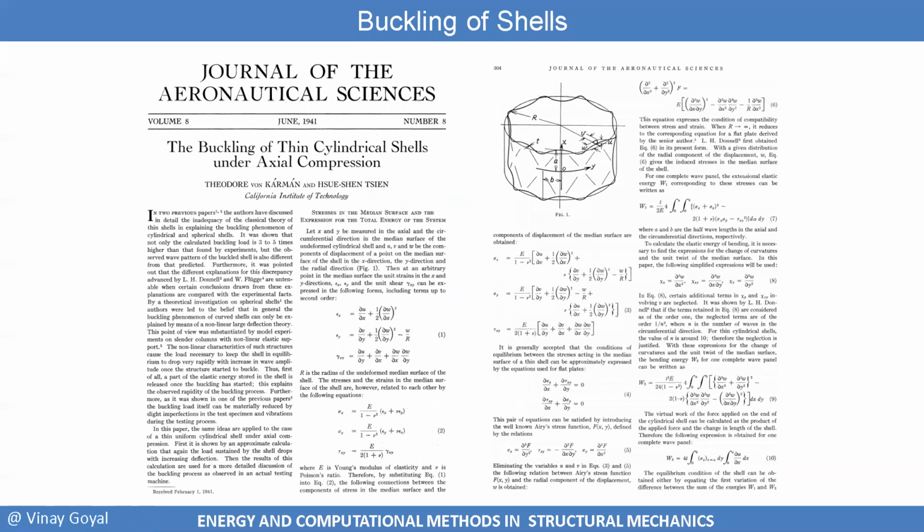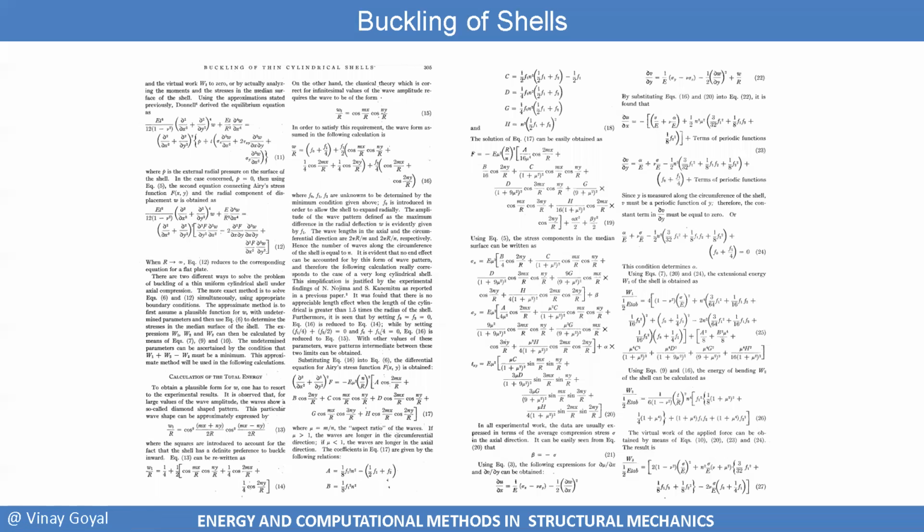I encourage you to look at these articles, pause the video, and download them. This is the original article by von Karman. And I feel like you will understand everything here because you learned so much so far. Here you're looking at the buckling of thin cylindrical shells under axial compression. I covered plates, but here you can see how you will deal with cylindrical shells. And you can see strains and stresses are being calculated. You can calculate the energy due to applied loads.